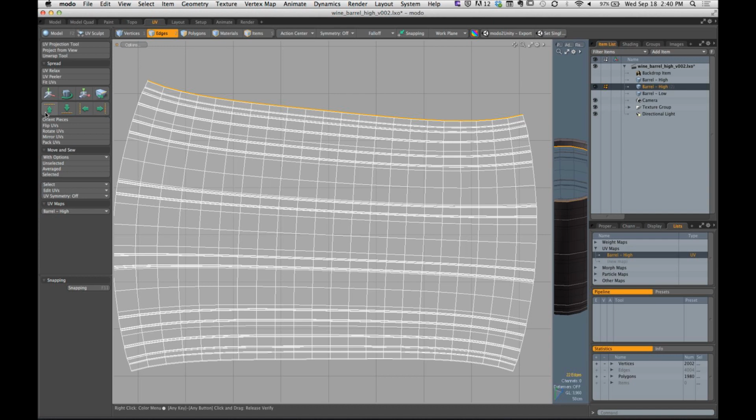It's not the nearest closest grid line, but I like the way you're thinking. It's going to analyze the highest vertice on that edge, okay? So it's going to very quickly go through, scan all of the vertices that I've selected, pick the one that's the highest along that axis or that has the greatest value, and align everything to that. And for me, it's going to be this corner one. Okay, it's going to be that one right there.